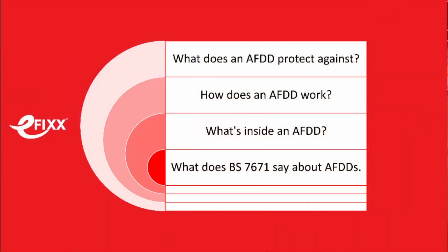So there we go. We've considered what an AFDD protects against, how they work, and what's inside of them, as well as what BS7671 says about AFDDs and where they need to be installed.